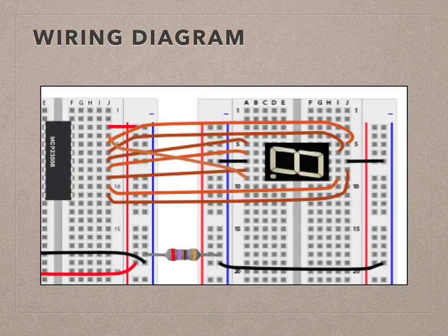This is how I have completed the wiring of my 7-segment display. Each of the lettered segments increments to match the GPIO pins on the chip, so that segment A is controlled by GP0, B by GP1, and so on, leaving the decimal point for last at GP7.